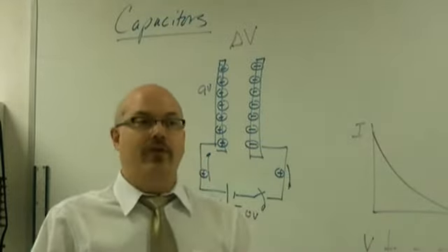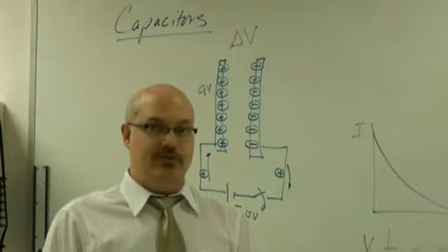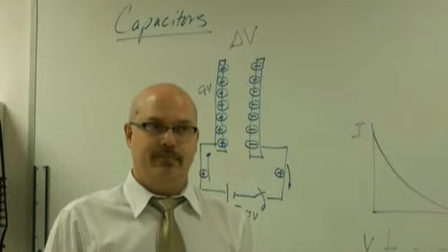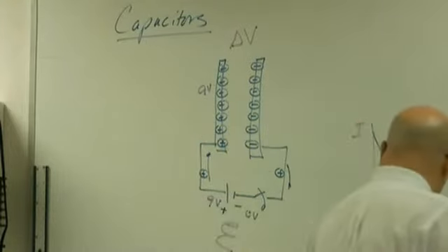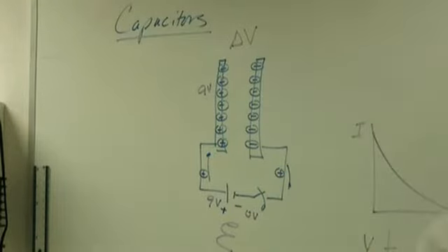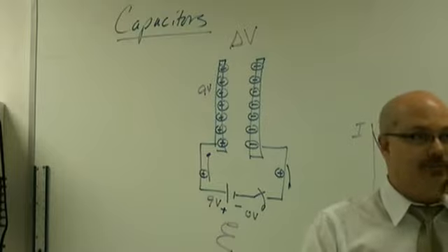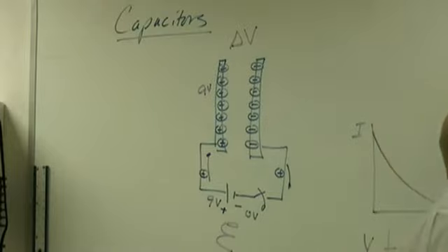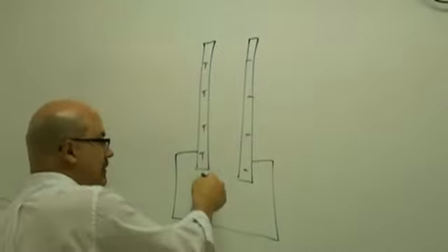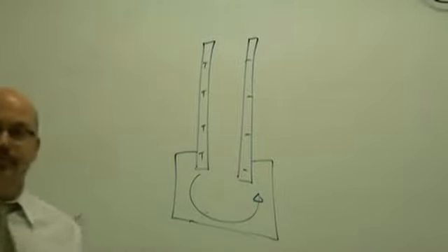Now, when will the capacitor ever discharge? Never. How do I discharge a capacitor? By opening the switch? So for instance, how could I discharge this thing? Put a resistor. Yeah, that will work. If I just connect the circuit, if I connect both sides, then what happens? High volts to low volts, and current will flow back this way.